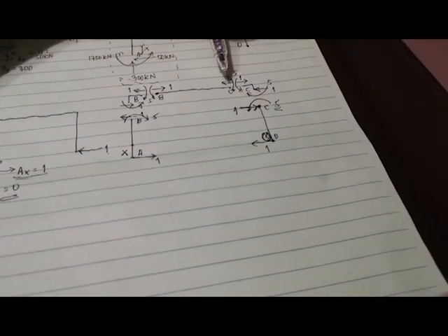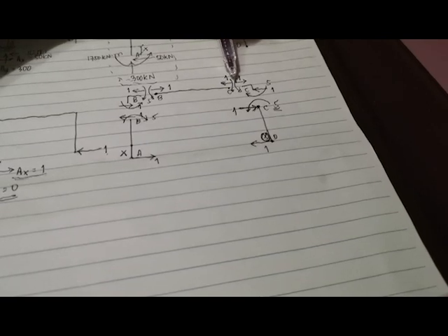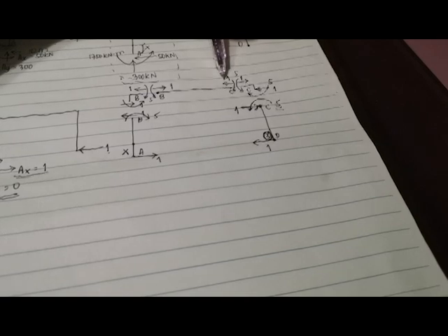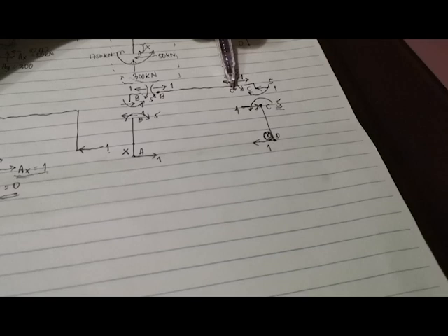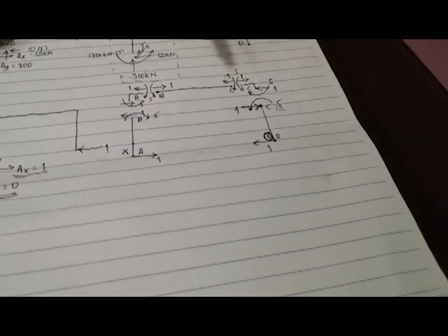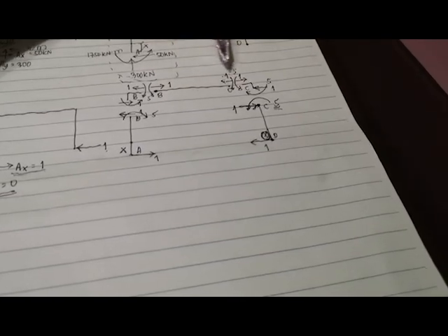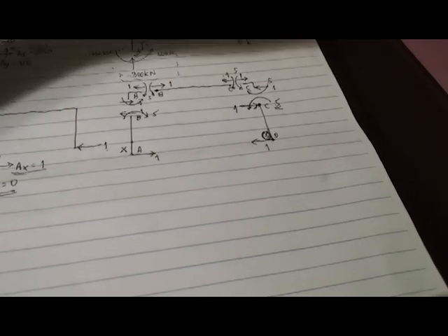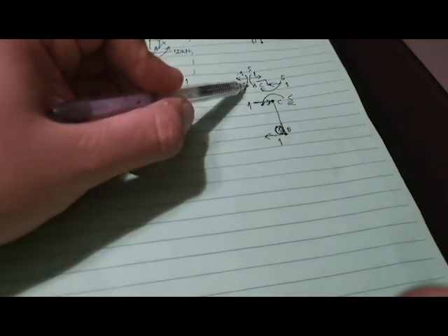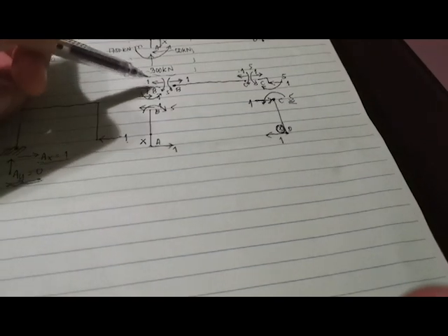Again, here at member BC and joint C, we have a load to the right. So therefore, opposite, there is a 5 kilonewton counterclockwise, therefore a 5 kilonewton opposite. And then at joint B, we have 1 kilonewton to the left, so we will have 1 kilonewton to the right here. Then we have a 5 kilonewton clockwise, therefore 5 kilonewton counterclockwise.